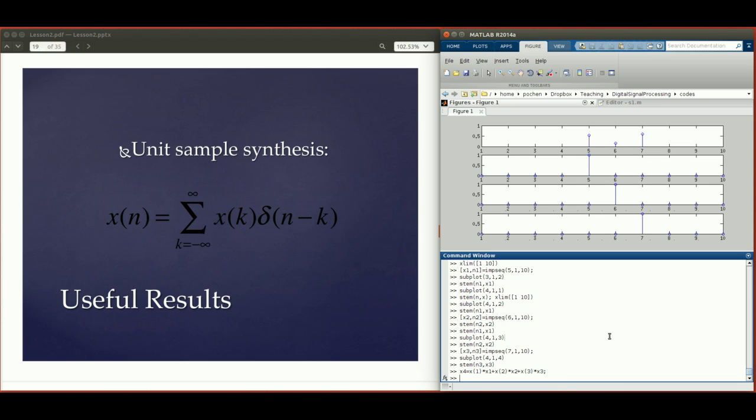So suppose I hold on. So suppose I subplot 4, 1, 1, and then hold on to the old plot, and then do another stem, but use a different color. I'm gonna do n x4. I'm gonna plot x4, but I'm gonna use red, right? So if those two signals are identical to each other, the red sticks are gonna be on top of the blue sticks, and you won't be able to see blue sticks anymore.